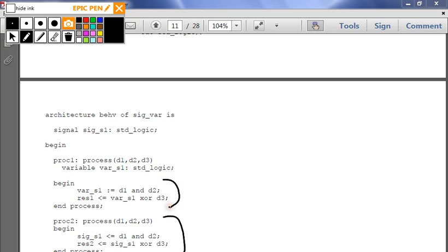What it looks like is the exact same code, right? But what ended up happening is this calculates it immediately without any delay. And this inserts delay, because the signal is actually a representation of a physical calculation, whereas the variable is just what it is. And so when you're simulating it, you have the variable immediately.